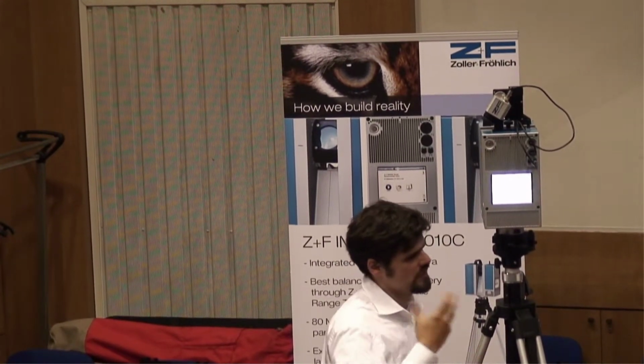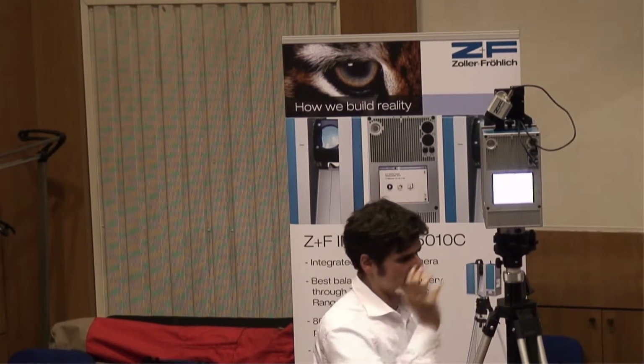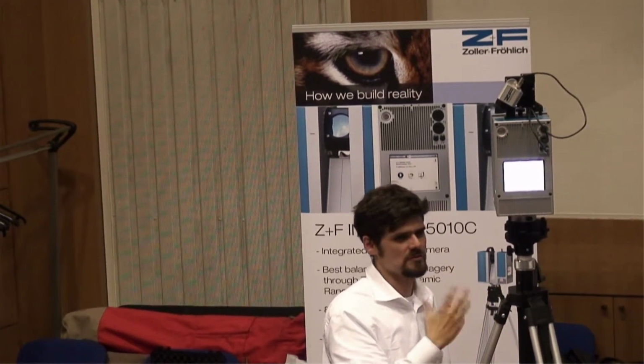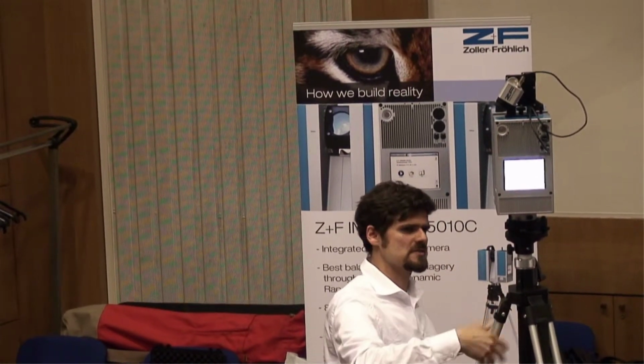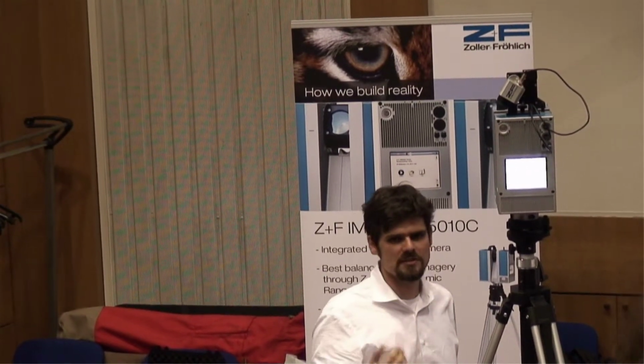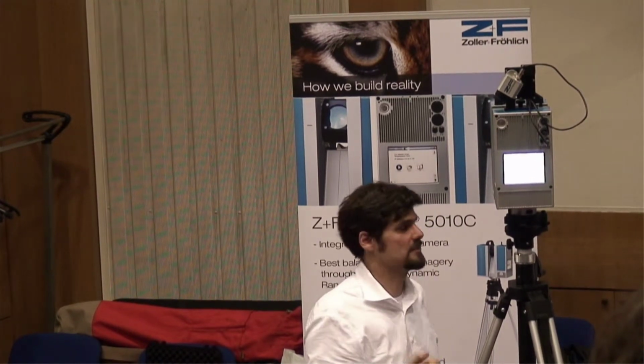If you're scanning normal environments, let's say up to 50-60 meters, the normal quality setting is completely fine. If you go beyond 70 meters, or if you've got very fine detail, you want to increase the quality setting and scan slower, so you've got less measurement noise, basically.